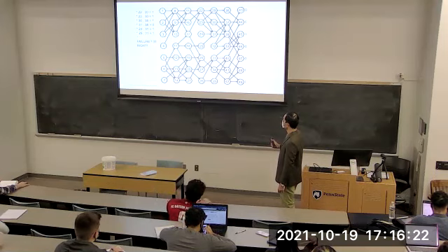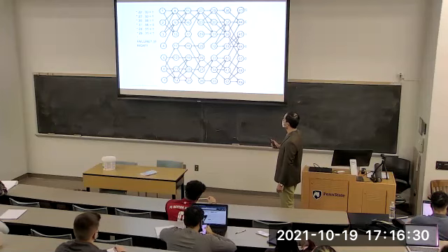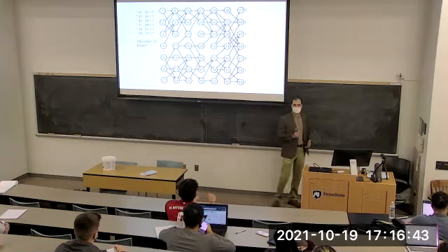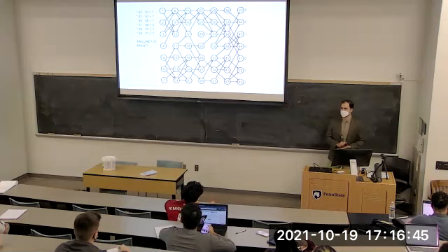So if it's producing 1, it's producing 1 for all outputs. And the same goes for 22. So this is giving 1, this is giving 1. 24 to 31, again 1. 25 to 31, again 1. There's only one possibility, that 31 is not working. So 31 is the component that is causing all of these problems.